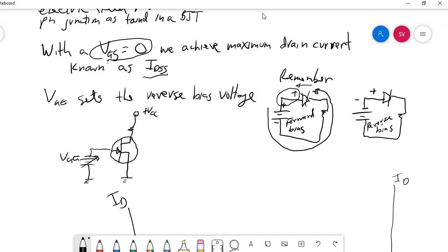In reverse bias, we basically widen the PN junction found in a diode. At the base of our diode symbol are our waiting holes or vacancies, which are positively charged, so they're going to be attracted to the minus end of the power supply. At the cathode end of our diode, we have waiting electrons, specifically valence electrons, because they have the loosest attraction to the nucleus of the atom, so it doesn't take as much energy to break their orbit from an atom to go into the orbit of a neighboring atom.